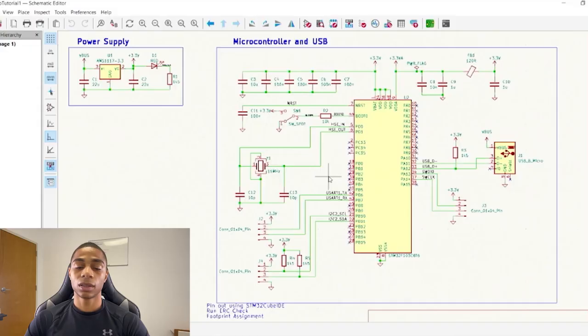All right. Okay, so now that we spoke about what a microcontroller is and we know exactly what microcontroller we're doing, we can go ahead and describe our schematic. So first of all, we have our VSS and VSSA here. This is our ground for our digital components, as well as our analog components inside of our microcontroller. And then if we go up here to the top, we have VBAT, VDD, VDD, and VDD. And this is power to our digital components inside of our microcontroller. And then VDDA provides power to analog components inside of our microcontroller.